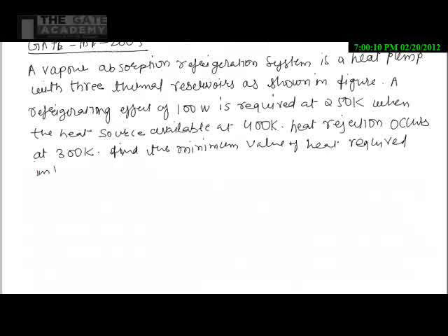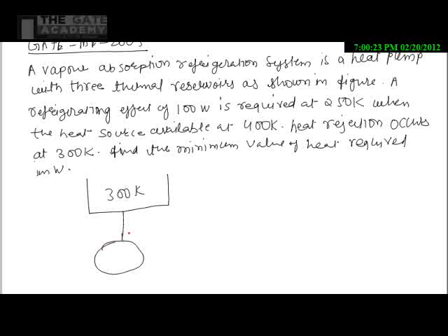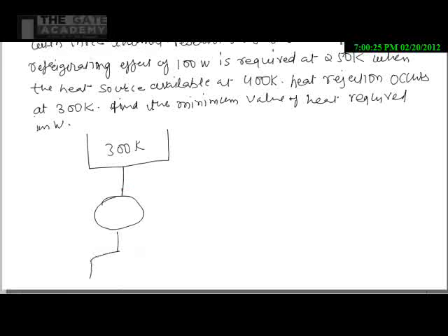So now let's draw the diagram first. Here I am having the 300 Kelvin reservoir. Here I am having the device. Here I am having the 250 Kelvin reservoir, and here I am having the reservoir of 400 Kelvin. So in this question, the refrigerating effect that is required is 100 watt.